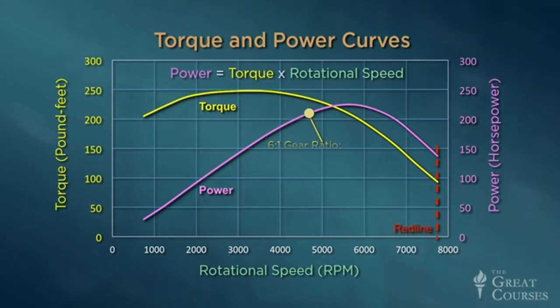On the highway at 60 miles per hour, our drive wheels would be rotating at 800 RPM, which means that the engine would be running at 6 times 800 or 4,800 RPM. That's pretty high on the power curve. And if we're just cruising at constant speed, we're really not using that much power, or at least we don't need it. Yet we're constrained to use it and to burn more gas than necessary simply to maintain our desired speed.